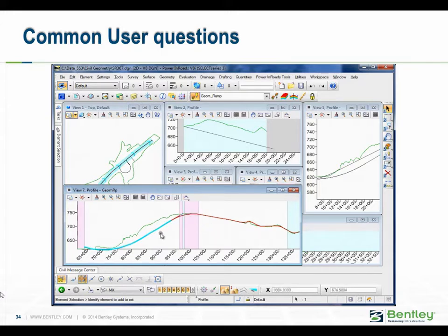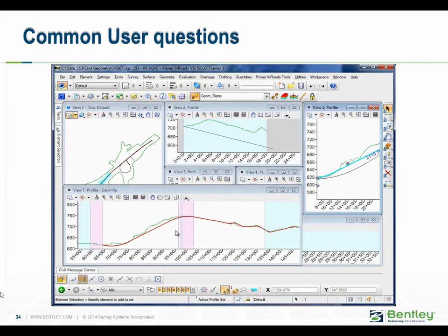But you'll notice this one has no element handlers because this profile is actually over here in the individual profile. So it remembers the relationship, or link, between the original profile and the new complex, and the same thing here. I can easily come over here and change this to a new one, and this one will automatically update.